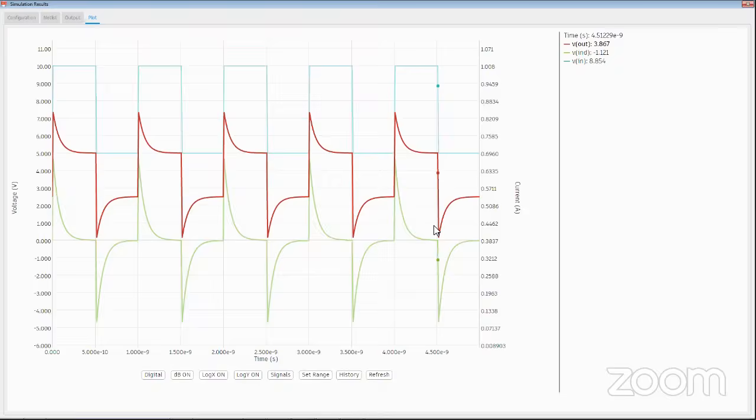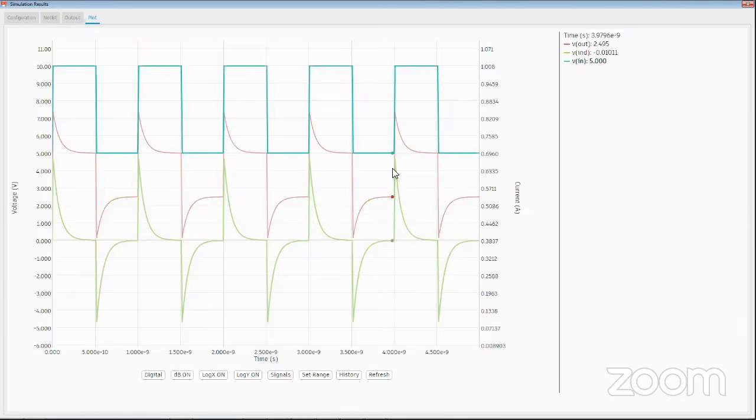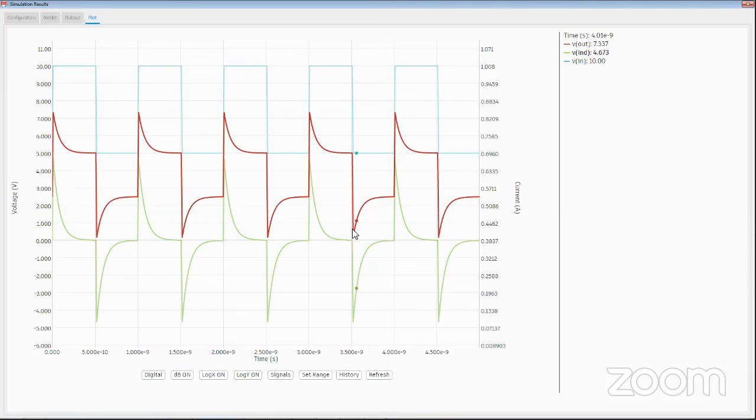So we go from a circuit that was exactly as expected, exactly as designed at 1 megahertz and no surprises, to, once you start going into higher frequency regimes, that inductance becomes important. And now you're getting this craziness.